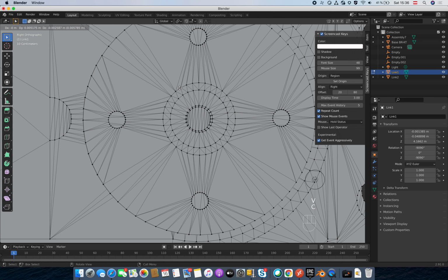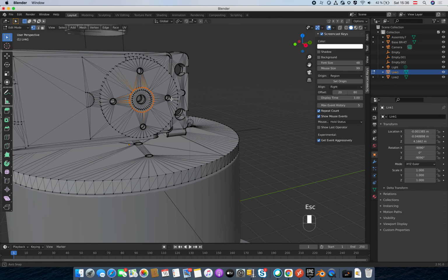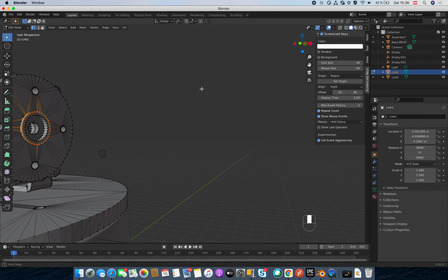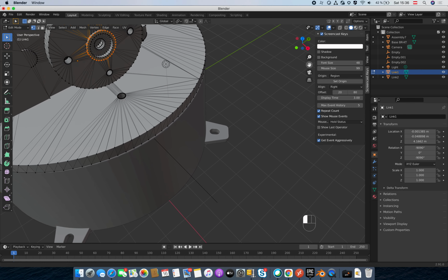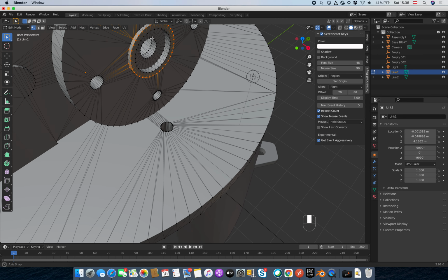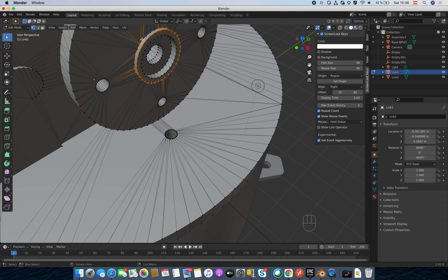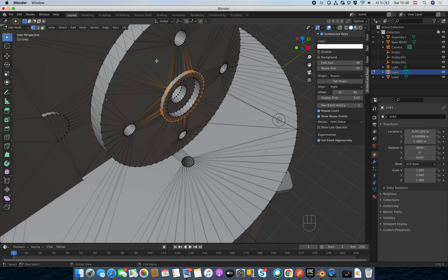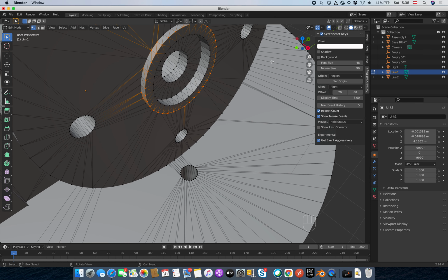And let's select, then let me make sure. Yeah, that's not good, because sometimes we have selected vertices of the base surface here, but I want to have only that circle there. So we need to click away again, and I need to do the selection again.